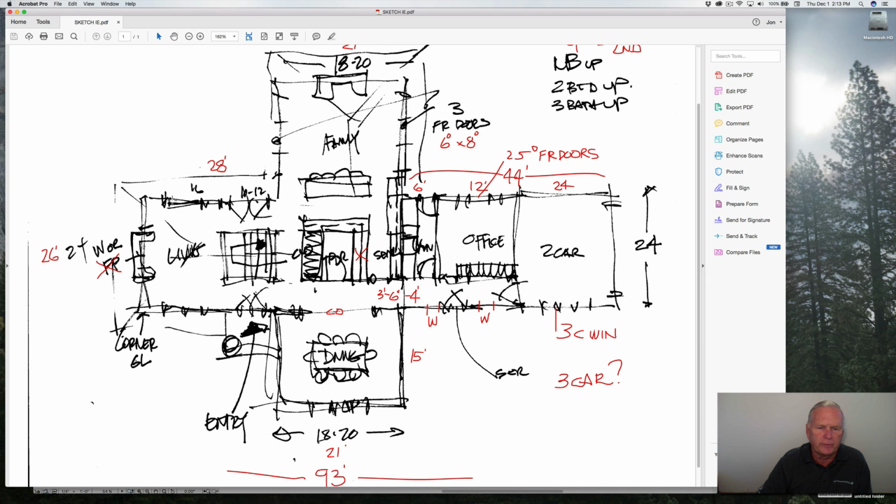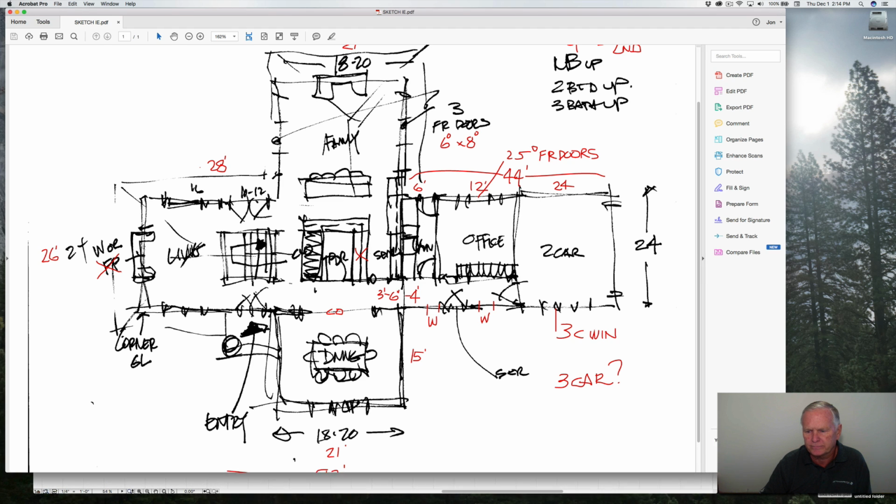And so the first thing we're going to want to do, let's go back and look at that PDF. And if you can kind of see, we have this cross plan of exterior walls. So a big horizontal box going across the screen and a vertical box going up and down on the screen. So we're going to put those exterior walls in. And to start off with, we're going to look over here. I've got 26 feet as the width of this box. Again, that is what I'm calling the box of walls. And then the length I've written down here at the bottom is 93. So 26 by 93. We're going to click back over to Archicad.